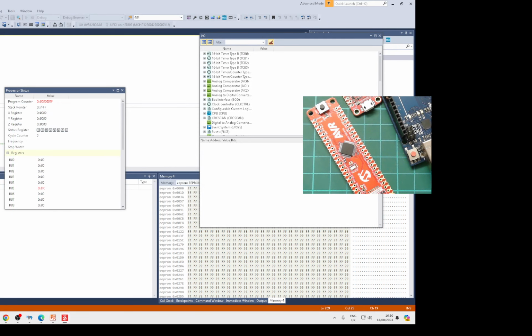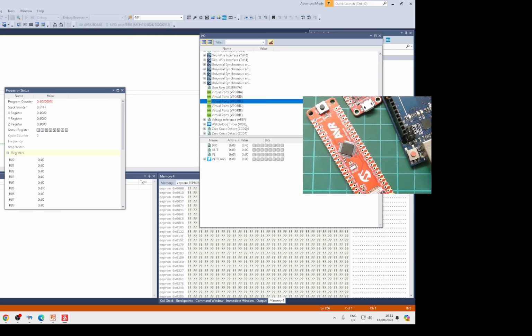The chip is sitting there. Very good. If we look on the screen, we can see that the Z register is changing. We can see that the I/O port, is it C, is set up. And here is the virtual port here, and that bit is changing. Oh, it's down in the loop, is it? It's waiting for me to push the button, isn't it?